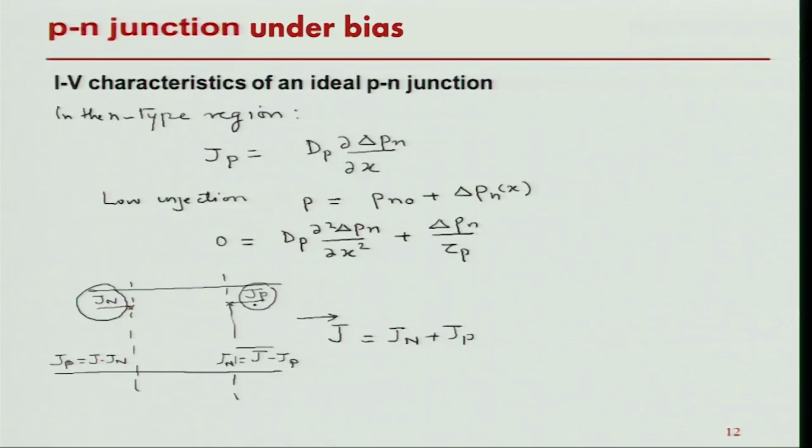All I am doing is injecting some little amount of carrier from P to N or N to P. And so, in the low injection regime, we are saying that whatever was status quo in the depletion region is maintained, and since there is no generation and recombination in the depletion zone, no generation of carriers, basically means whatever current I am getting here for the electrons or for the holes is going to be the same in the depletion region.